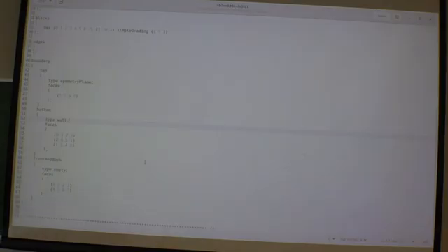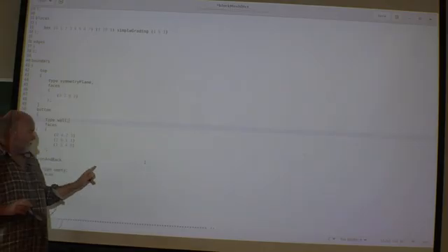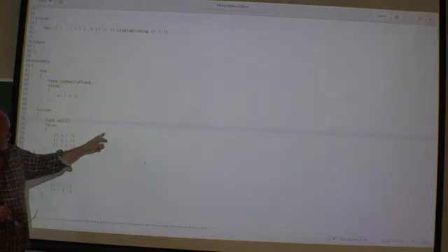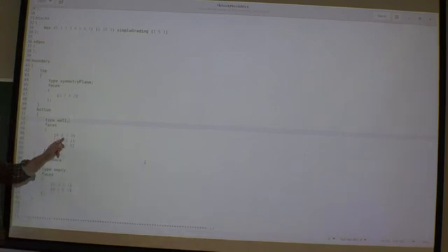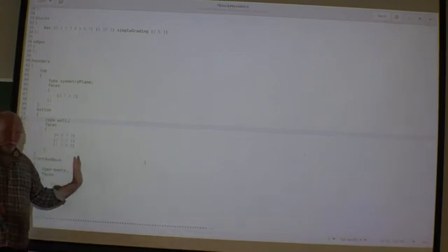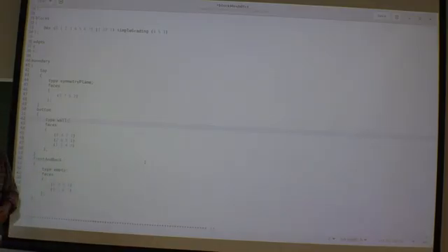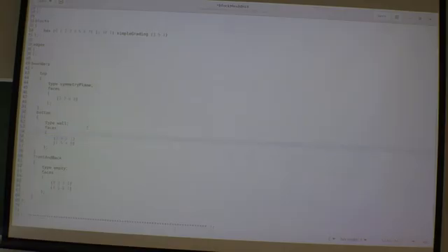Well, I don't have all of them, do I? Now we have to remember how OpenFOAM was organized. Well, you have a 0, 1, 2, 3, if I recall correctly, and then you have 4, 5, 6, 7. So 0, 4, 7, 3. That should be the left face. That's actually the inlet, isn't it? So let's copy that one to the inlet, or move that one.